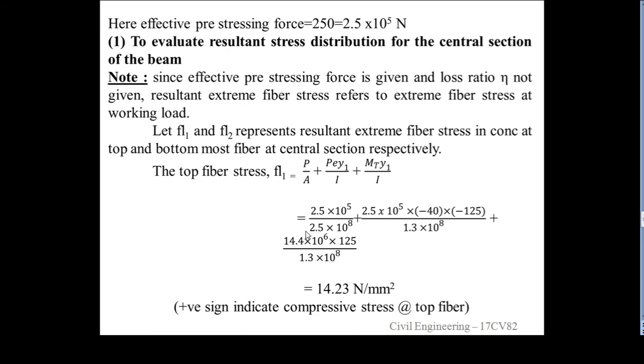FL1 equal to 2.5, that is pressure force, into 10 raised to 5 divided by area of cross section 2.5 into 10 raised to 4, plus 2.5 into 10 raised to 5 into eccentricity minus 40 into minus 125, that is top fiber stress,